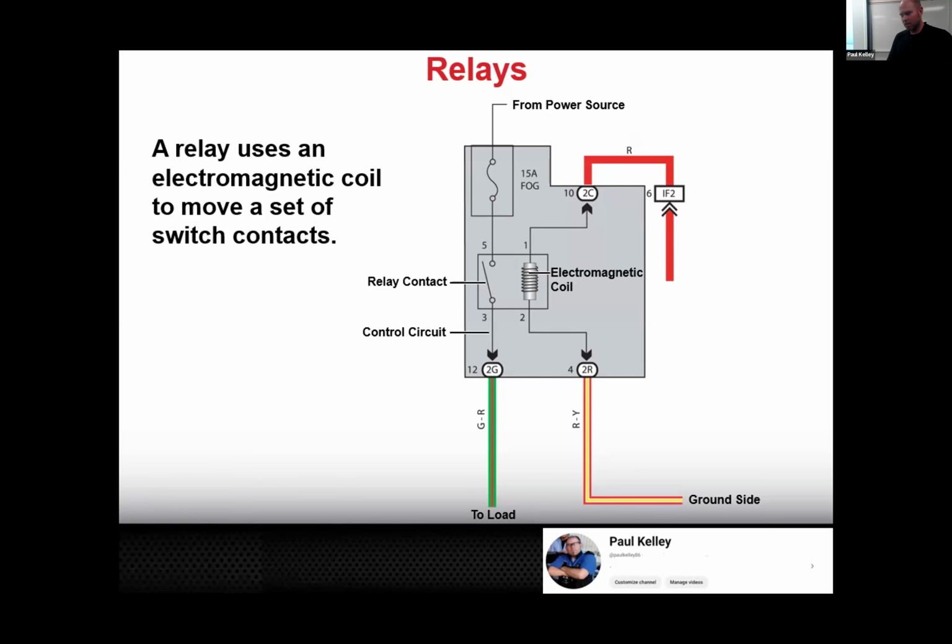The negative to that is if there's no physical relay and it's a solid state relay, which means it's really a transistor, you can't replace it, right? So back in the day, techs would be like, oh, I know how to diagnose a relay. I rip the relay out and I switch it with another one, and if it fixes it, it fixes it. And that's actually true, and there's nothing wrong with doing shortcuts like that. But if it's a solid state relay and it's built into the module and it's really a transistor, you can't rip that out and sub a new one in there.